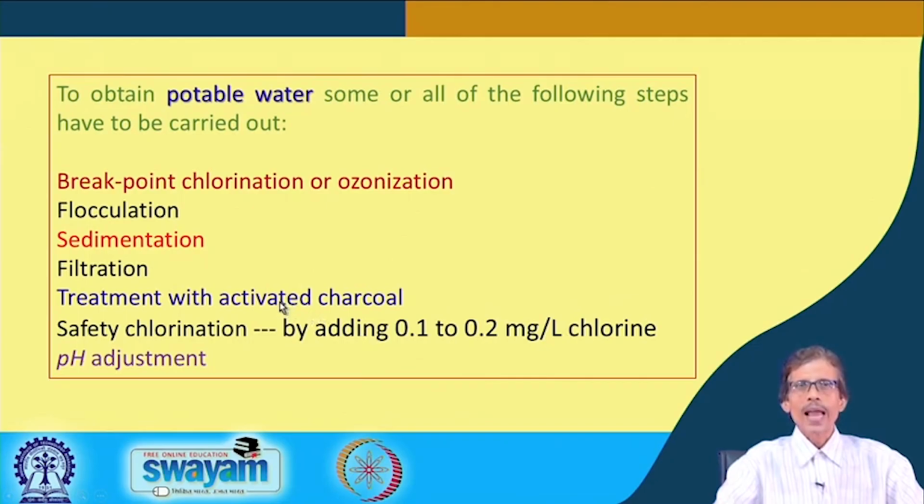If we activate the charcoal by burning off unwanted material adsorbed over it, we can utilize that charcoal packed in a filtering column, like an ion exchange column. We can utilize that packed column for the filtration process, where the bigger particles cannot pass through the interparticle passage of the charcoal material.